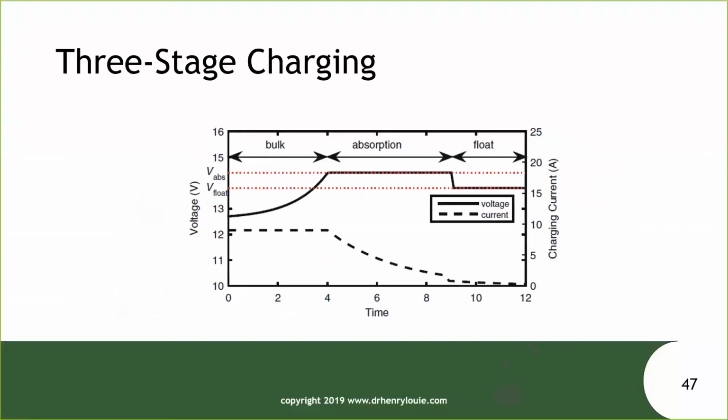And the current then will vary. As soon as we get to the absorption stage, the current starts to taper off as the state of charge gets closer and closer to the absorption set point.